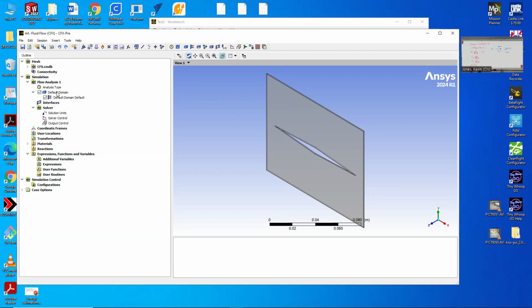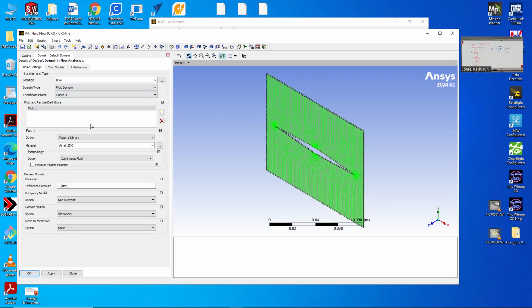So the first thing to do is to go ahead and set up the equations that we need to solve. Let's go in here. When we went from incompressible to compressible, remember in incompressible, all we needed were the momentum equations and continuity, and we had closure. But when we go to compressible, we throw in rho as a variable, and so we have 4 equations and 5 unknowns. We're in trouble. So what do you have to do? You need a couple more equations, right?